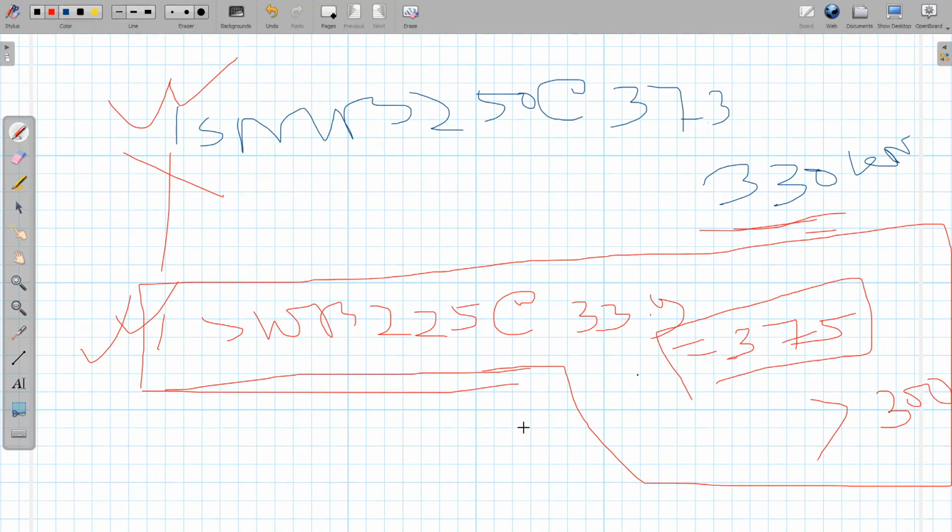The same steps you need to apply for the strut also. The only thing is that you have to check what type of strut it is and what the support conditions are, and based on that, how much permissible compressive stress to take, whether 100% of sigma SC or 80% of sigma SC. And you have to take the effective length depending on the end condition, that is whether rivets are used, single rivets, or welding, or both are used. Otherwise the remaining design steps are almost the same.